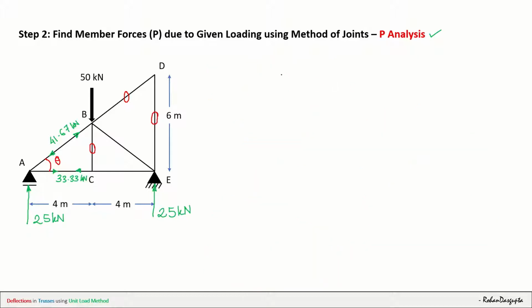All right, so now that our drawing is done, I have removed the calculations and now two members are remaining, that is CE and BE. So let us take a joint E so that directly we can find out both the values of member force EB and EC together. So I am again going to draw the free body diagram of joint E.